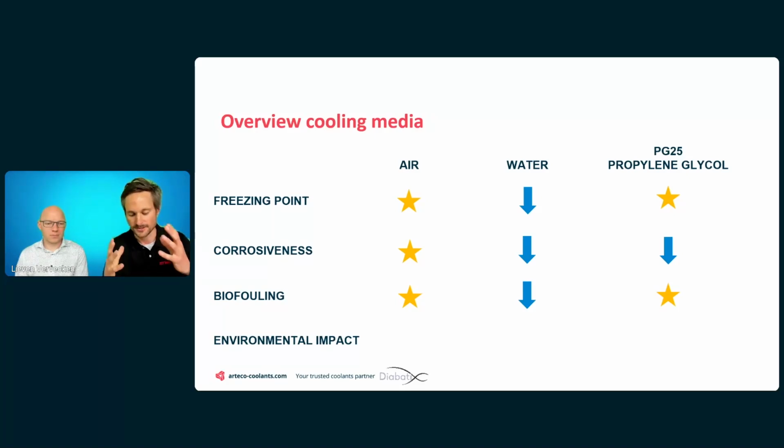And by proliferating, they actually form a biofilm on your cooling system, preventing the heat from properly being transferred. And they might also start to block any narrow channels. So with a pure water-based product, you could get the biofouling. It would allow any microorganisms to proliferate. And that's actually also the reason why 25% of propylene glycol is being added to the product to prevent that from happening.